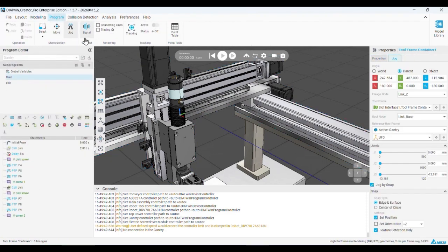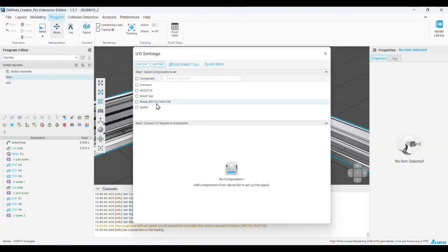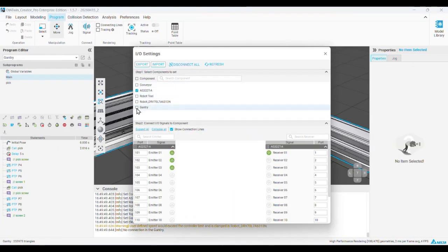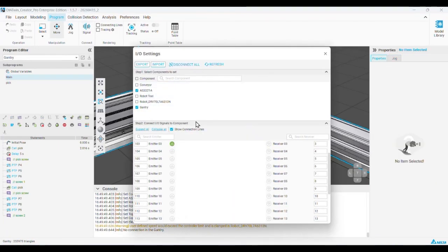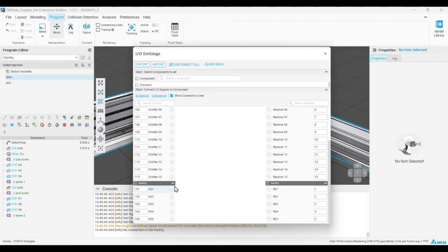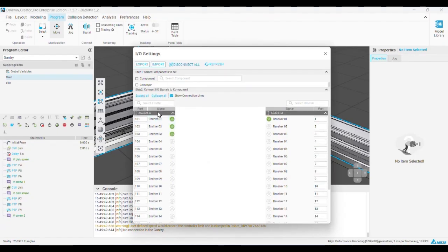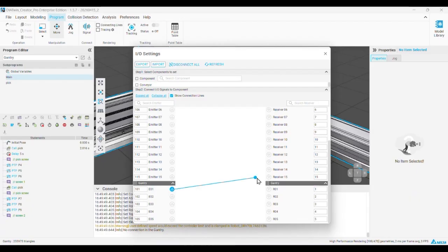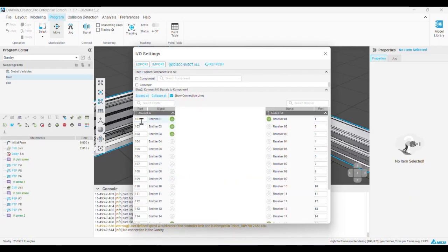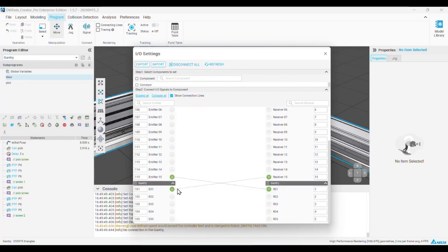If you want to use a signal, for example when a PLC needs to communicate with our Gantry, like here you can see here's the Gantry and here's the PLC, maybe you can also make a cross right here so that the Gantry is able to communicate with the PLC. That is handshaking: waiting for a process to be done, waiting for something else, and then I can start my process, finish my process, and get the return value back by using the cross right here.